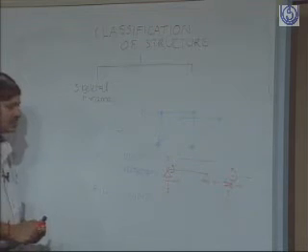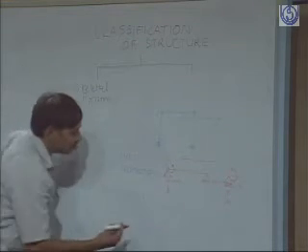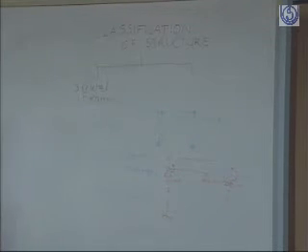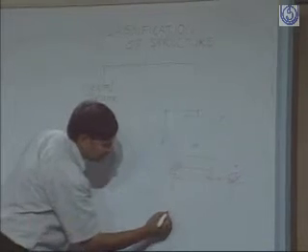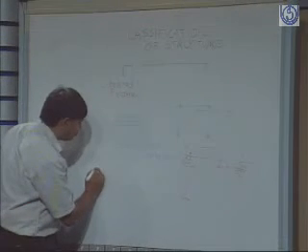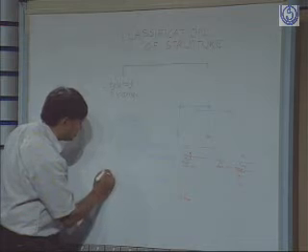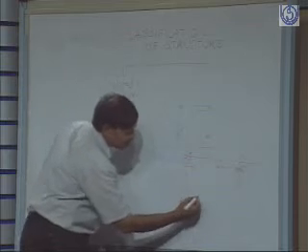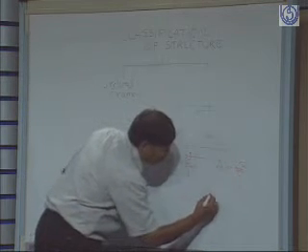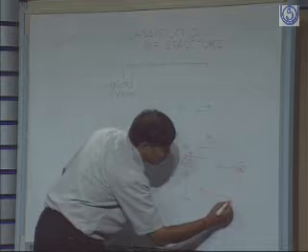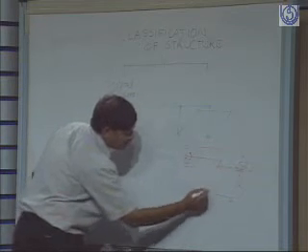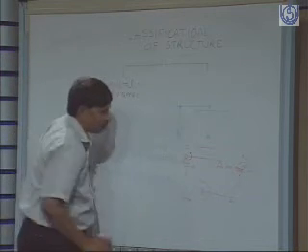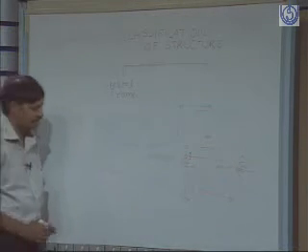Whereas in a rigid joint, how do we show a rigid joint? Say this is a column and it has been fixed here. We also call it a fixed or rigid joint. So this is a fixed end, or this is a beam. Say here it is supported at a roller. So this is a fixed end. What does this do? This restrains all types of movements in all directions.